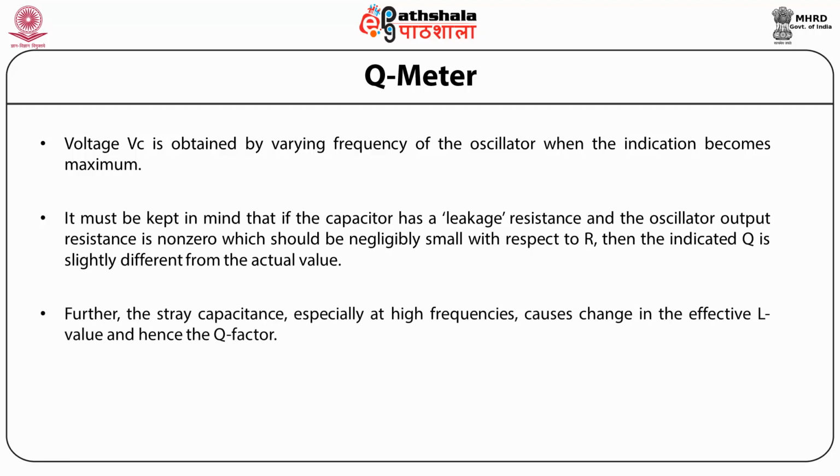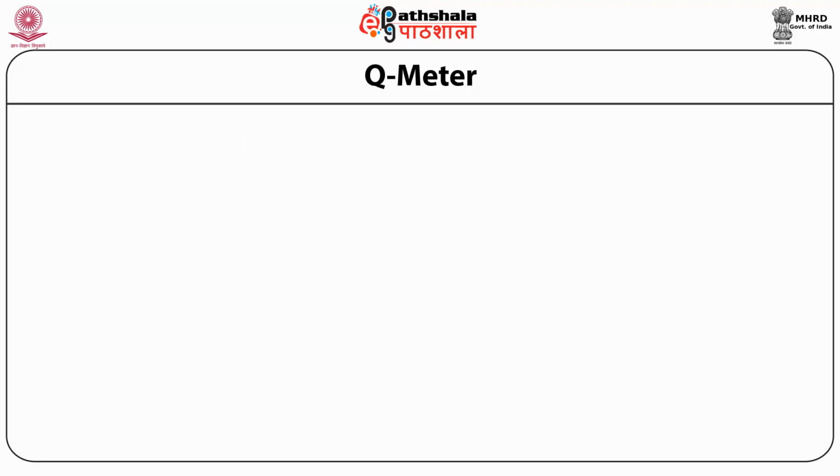Further, the stray capacitance, especially at high frequencies, causes a change in the effective L value and hence the Q factor. The interwinding capacitance of the coil behaves similarly.